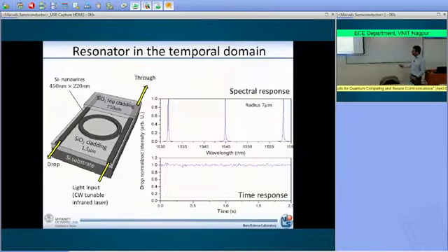Okay, so in this case you have a microring resonator in the add-drop configuration. Just to give you numbers here, this is the typical silicon nanowire. Here is the silicon oxide top cladding, 750 nanometers, and the radius of the microring resonator in this case is 7 micron. Okay, yes?